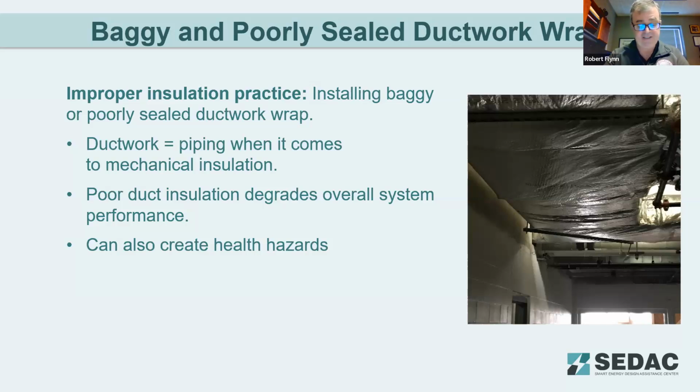Ductwork that isn't tightly sealed can allow condensation between the ducts and the insulation. This can harbor mold and mildews. In return ducts, it can be drawn into the system. For supply ducts, air pressure can force these pollutants out into the plenum spaces of rooms.